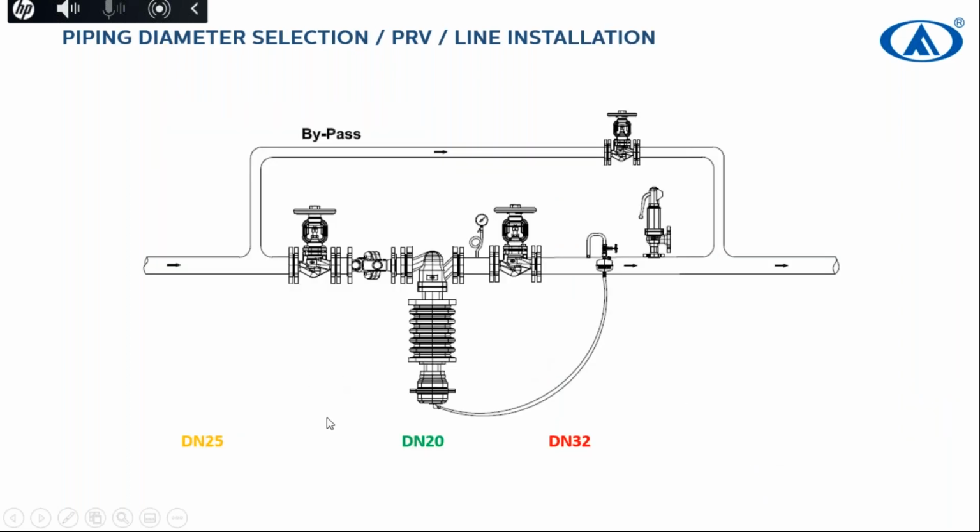It says a lot. You can just count it like this and you can just apply it in your pressure reducing stations. If it's pilot operated or, as you see here, spring operated, it can be DN100 as yellow is shown, or it can be DN200 as it's shown in red, or it can be DN50 for green.